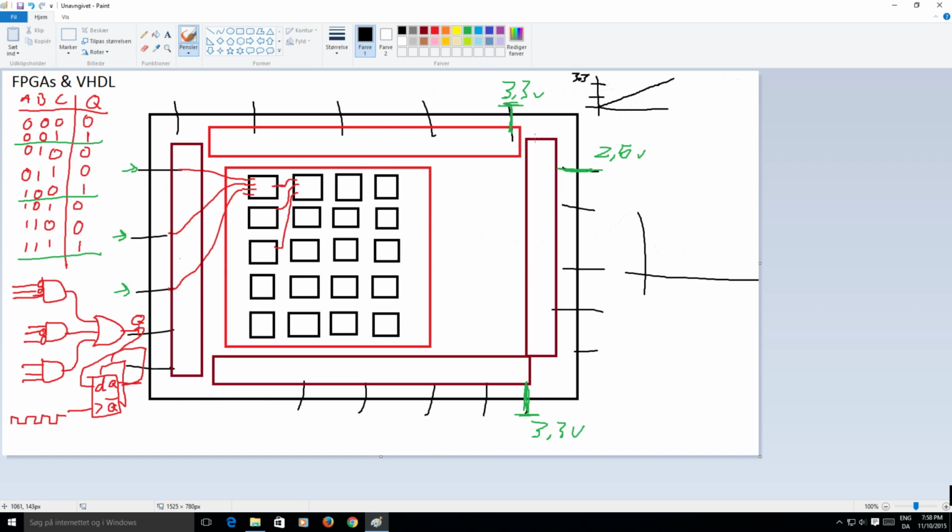And the differential doesn't really look at the voltage. It looks at the difference of the 2 pins. So if you have one voltage there, and it then does that, and you have the other voltage here, and it does that, then it will look and see that this pin is higher than this one. That could represent a 1. And here they change. So the other one is now higher than this one. And that would then mean a 0. You can see here, first of all, we get double the slew rate because both pins are changing. And also the voltage difference between these two can be very little.